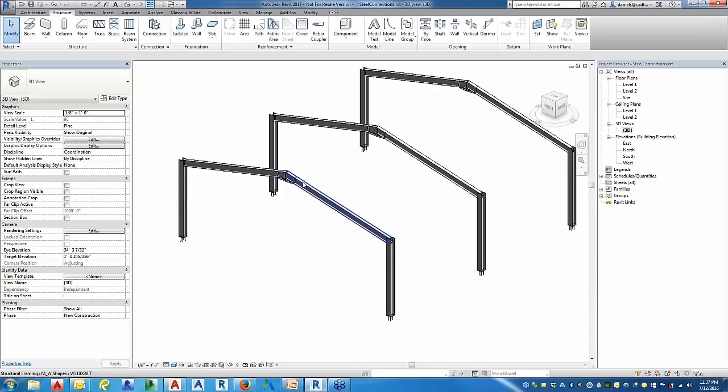And obviously from here you could also bring these connections to analytical software such as Robot Structure, and I think there's that other one, React Structures. I think that one might actually be replacing Robot Structure. I'm not sure. But those are some great analysis software to use basically right on top of Revit. It's really easy to export and import files into each other, and so that's pretty much the basic workflow for steel connections there.